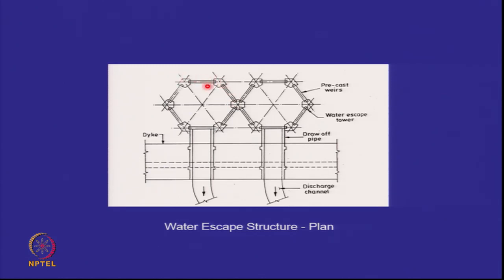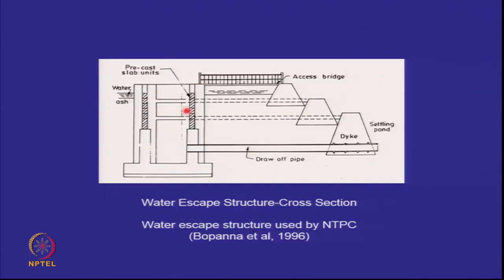They have these precast slabs which can go down grooves. I'll come back. So the precast slabs are being placed. They're continuously being raised in increments. And when you put the precast slab, you send somebody in to seal the joints. So when the slurry is at this level, water is overflowing from here, then they put the first slab, then the second slab, and it keeps on going higher and higher like that.